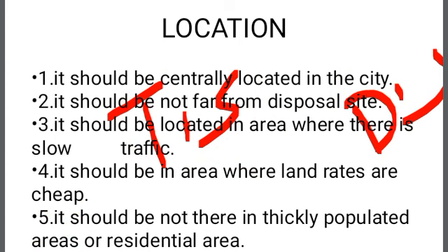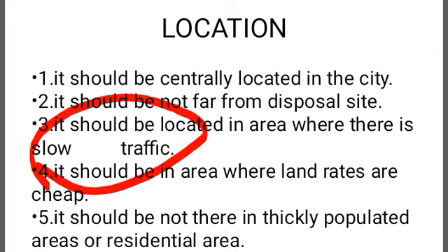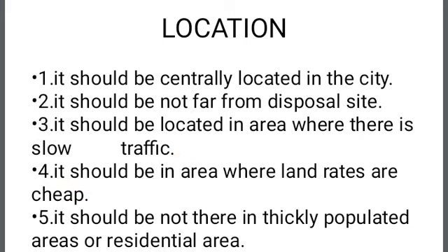Next point, the transfer station should be located in an area where there is slow traffic. Generally the transfer station is provided in such a way that there is slow traffic. Next point, the transfer station should be in an area where land rates are cheap.